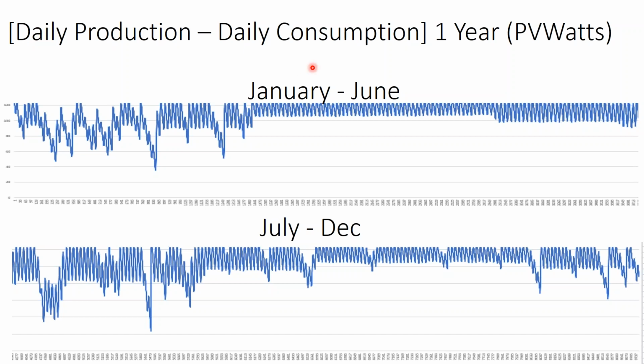What we can see is in March and April and May, it doesn't matter. It's mostly sunny days, and we're always slamming the solar array back up to the top. Here we're getting into summer, so we see our air conditioning loads increase, but we're still getting back up to the top. Then all of a sudden in July, we get maybe a hurricane system come through, so we go a few days without sun, and our July air conditioning loads are so large that the array can't charge back up to the top for a few days until we get completely clear days.